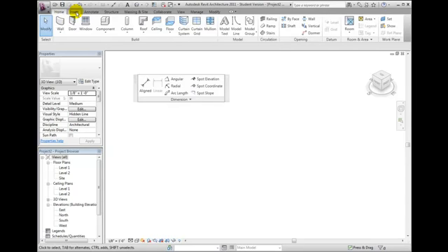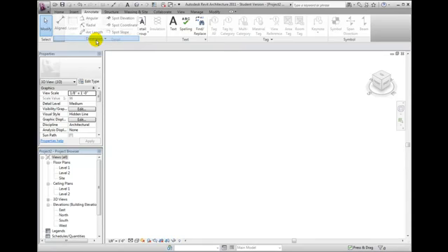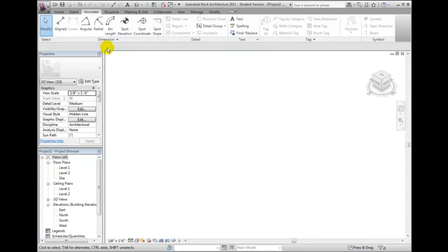To return a panel to the ribbon, hover the cursor over the panel until you see sidebars, and then click the Return Panels to Ribbon button in the upper right corner. This will return the panel to the proper ribbon and location it came from, even if that ribbon is not currently visible.